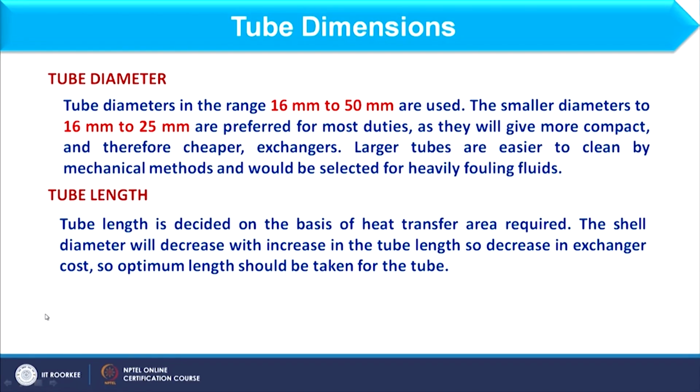However, the complete length can be obtained by adding the tube length, the tube sheet thickness and the cover size also. Accordingly the complete exchanger length can be finalized, but as far as heat transfer is concerned, tube length will be equal to the shell length.